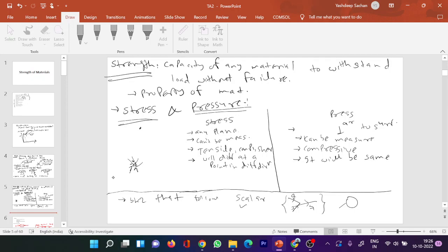So at that time you are applying pressure, then stress would be there, na. It is a completely rigid body, they told. Yes sir. Sir, if it's a rigid body, then Young's modulus would be infinite, and the stress would be infinite. So the deformation would be zero, because it is rigid. E would be infinite, in PL by AE, so deflection would be zero there. Any deformation would be zero, but stress would be there.